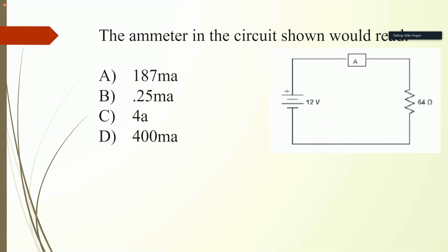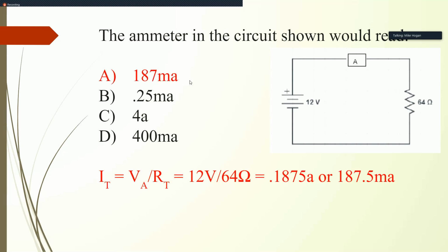Okay. So there's two steps, right? You do the math and it comes out with something that is 0.18, whatever. And then you've got to convert that, right? The 0.18 to milliamps. This is another great example. Instead of representing it as 0.18 amps, let's go ahead and do the conversion. Move it 3 places. So this is going to be times 10 to the negative third, which is 180 milliamps. Yes. Very good.